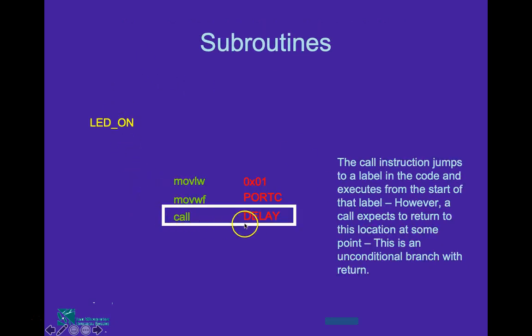Now a subroutine call delay. The call instruction jumps to a label in the code and executes from the start of that label. However, a call expects a return to this location at some point. So this is an unconditional branch with return. We will discuss the code for this later on in the next lecture.